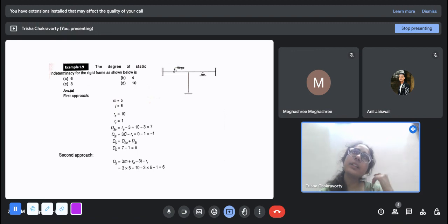Remember, in week 1 or week 2, when we were working with bending moment and shear force diagrams, at an internal hinge we get an extra equation. So this is subtracted. The total number of unknowns minus the total number of equations we get as 6, and from this formula we get the degree of indeterminacy. The degree of external indeterminacy remains the same, whether it is a truss, a beam or a frame structure. The concept of external indeterminacy will always remain the same.